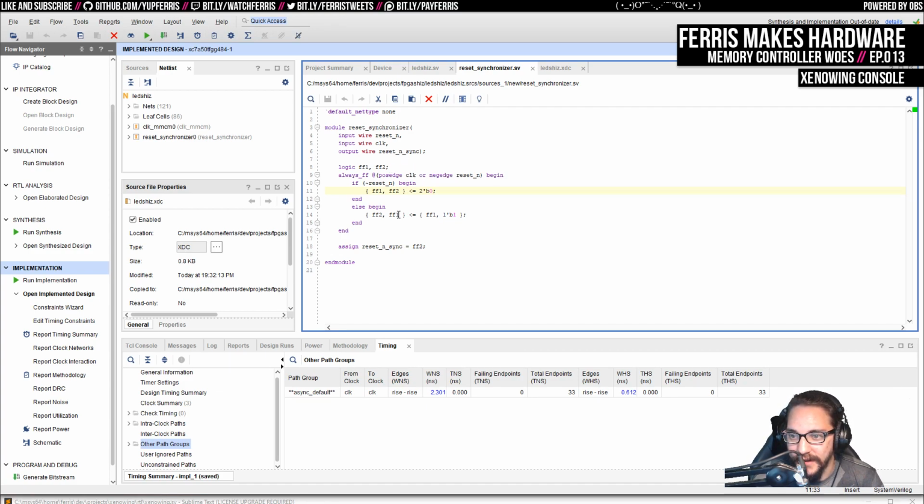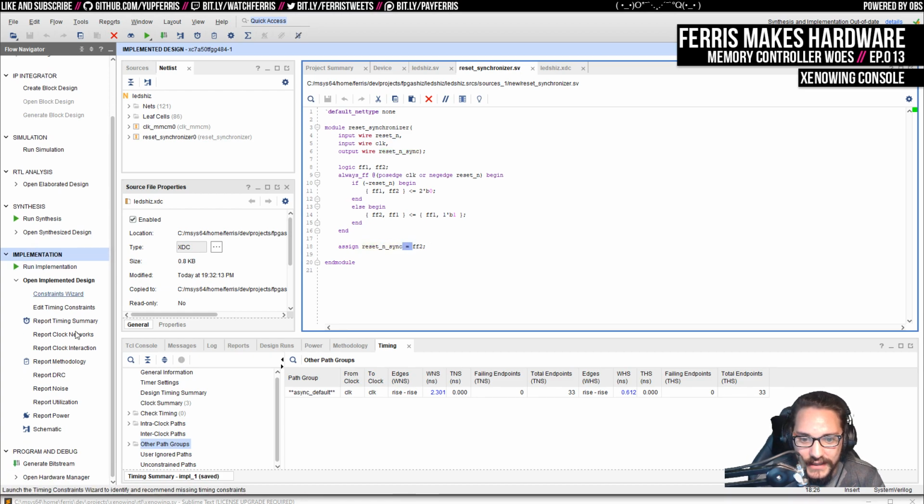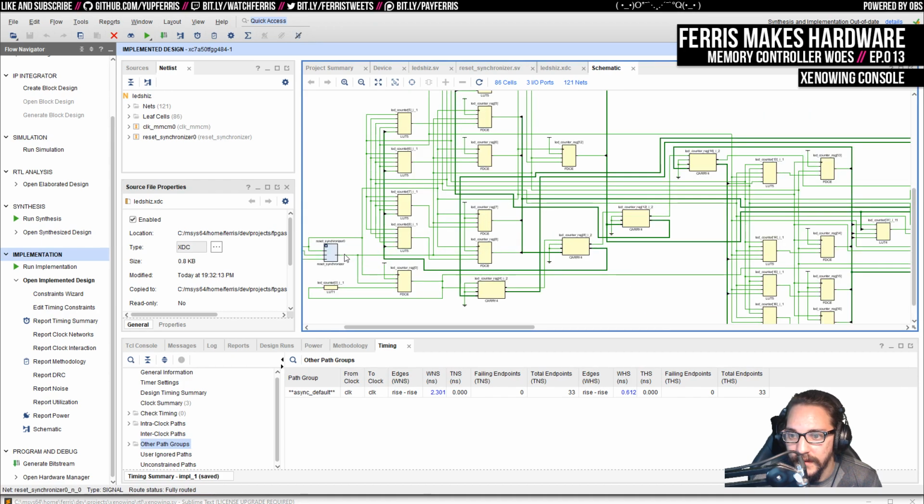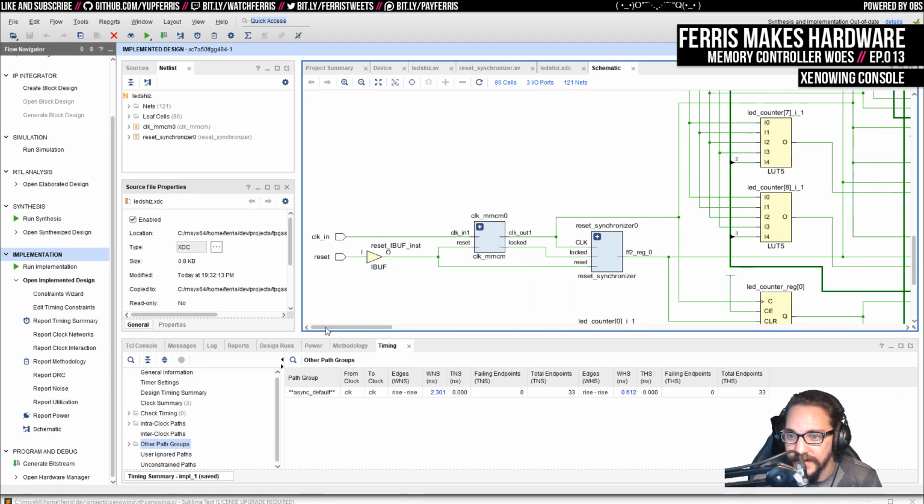And then otherwise on the clocks, we use this syntax to shift this high value through the 2 flip-flops. So it'll go into FF1, and then on the next cycle it'll go into FF2, which is what our output is. And we can see it in the schematic as well. If we go in here, here's the synchronizer. So here's my input for the reset, and there's the clock. And the clock coming out of the module is the one that we want to synchronize the reset to.